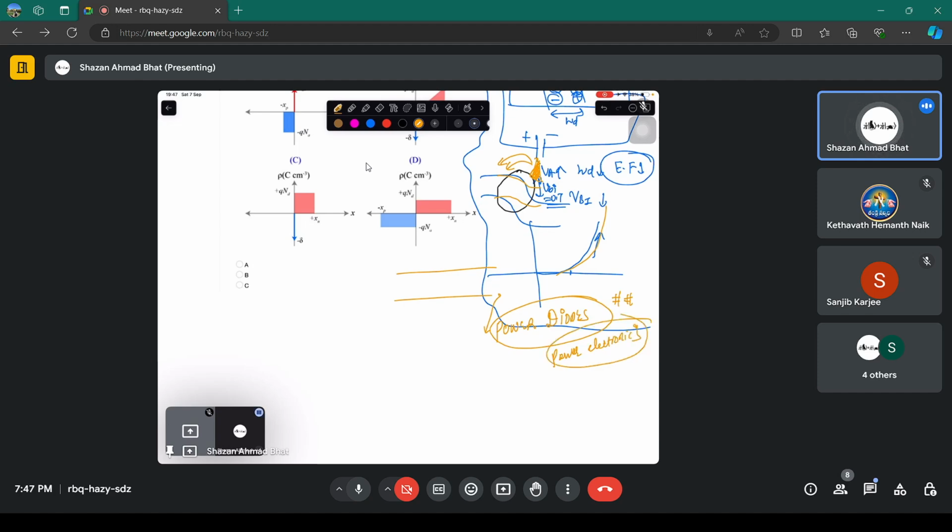These diodes can handle a current of the order of amperes, but the diodes we study mostly in electronics, in semiconductors, are not made to handle huge currents and huge voltages. If you want to make a diode which is going to handle huge currents and huge voltage, we have to modify the diode in terms of doping, maybe add another region or something like that. Then that makes it a power diode.